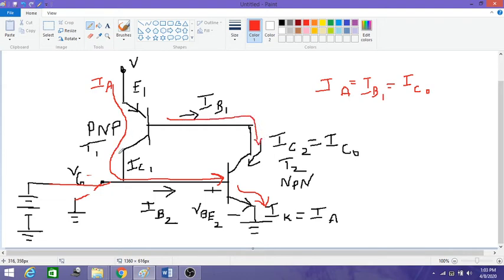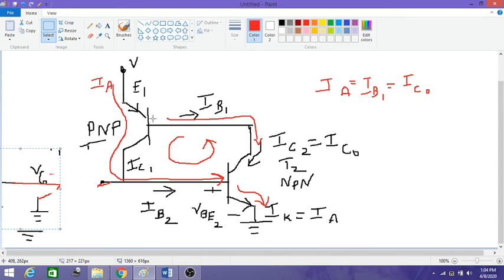And thereby there is a small base current flowing like this, and when IB1 is equal to IC2, T2 turns on, causing a large collector current to flow, and this in turn will increase IB2. As this IB2 increases, it is a regenerative process, in a loop. So even if we disconnect the gate, there is a large amount of base current at the transistor 2, which is equal to the base current of IB1, so that keeps the transistor T1 on as well as the transistor T2 on.